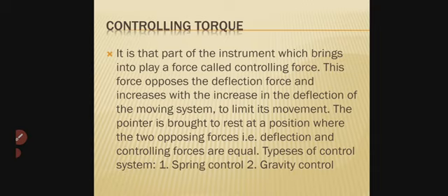If we are not provided the controlling torque, then the pointer once deflected would not return to the zero position on removing the deflecting torque. It will stay at the reading where the electrical quantity value is measured, and never come back to the zero position.